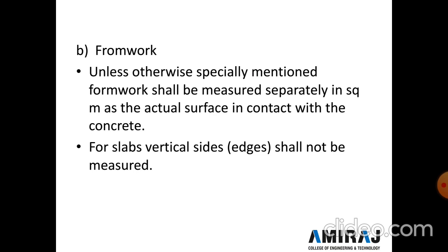So vertical side, what is vertical side? When we construct a slab, first we prepare a lower portion of the slab, and the entire area is covered by a 12 centimeter to 15 centimeter height of wooden plank. This plank is not included in the measurement.